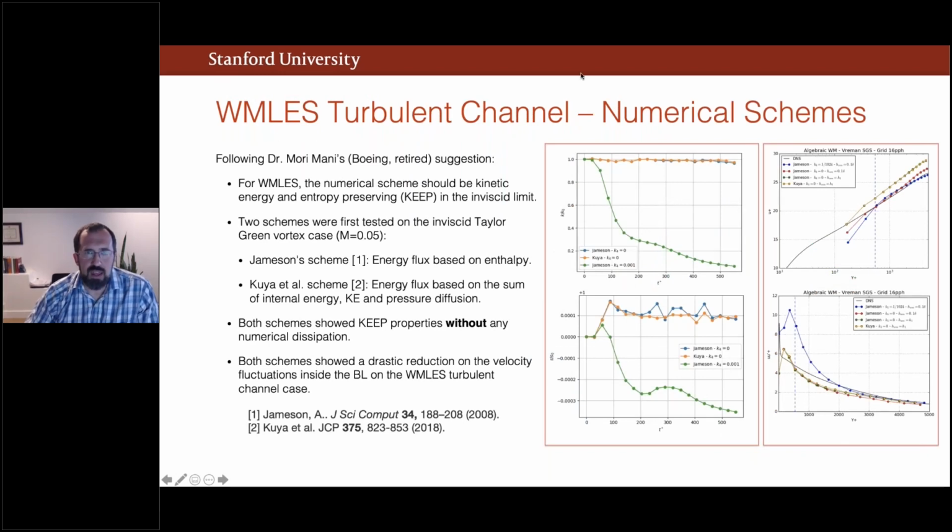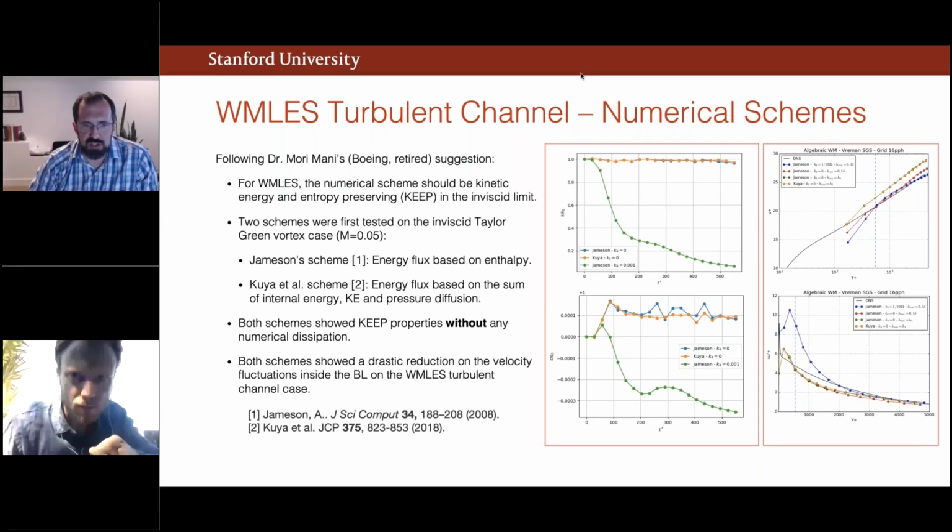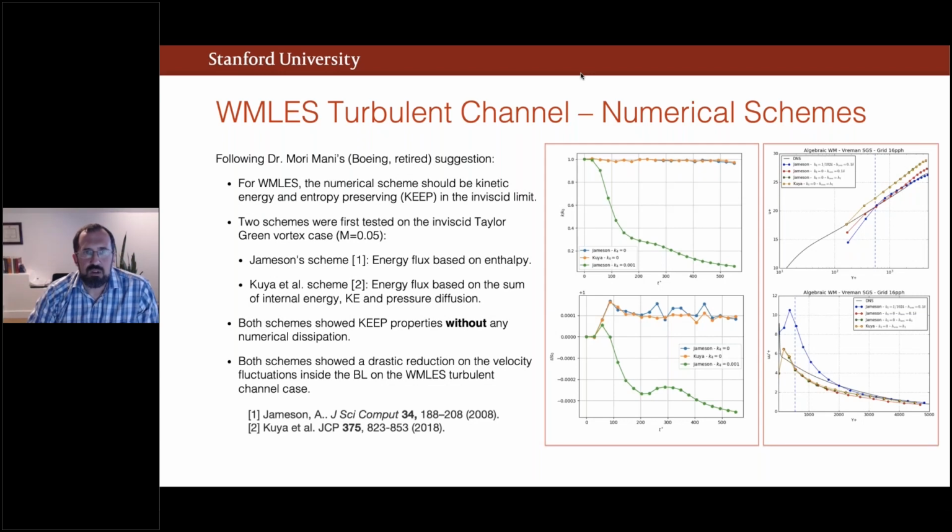So one other thing we looked at, in addition to wall model exchange location, was the numerical schemes in the plane channel flow case. Specifically, we looked at kinetic energy and entropy preserving, or KEEP, schemes. Some of those schemes are mentioned here. We first tested these schemes on the inviscid Taylor-Green vortex case, which you can see in the left-hand plots. And then we applied them to the wall model plane channel case, and you can see some results over here on the right.